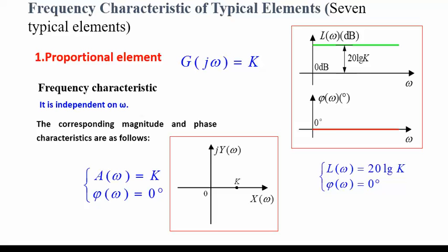We don't have any other possibilities. So we have either a constant, a pole at the origin, a zero at the origin, a first order pole, a first order zero, a second order pole, a second order zero, total 7. So we deal with 7 different things. Now in the Bode plot, you can do these individually and stack them up, or you do addition and subtraction. So any complex transfer function can be broken into individual terms that you do the Bode plot for, and you add these Bode plots. Okay, you add them, and you construct your system.